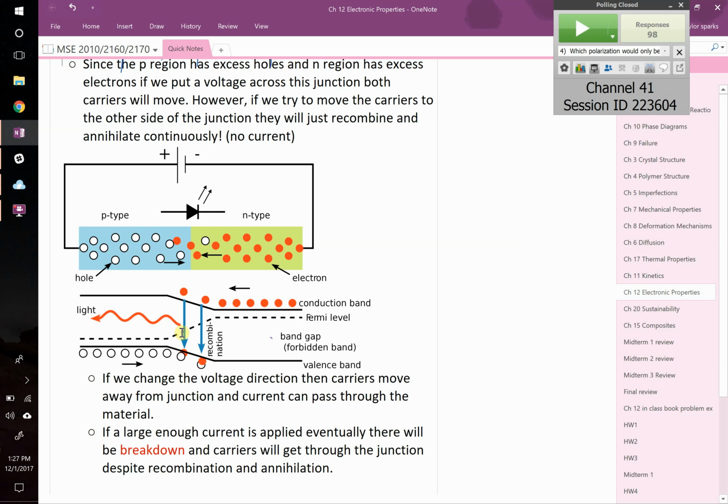So that's an LED. That's all it is. An LED is just a PN junction. You're forcing electrons to fall down and fill the valence band from their conduction band, and it gives off light in doing so and heats up a little bit. Any questions? So these devices that seemed a little bit like magical and like only electrical engineers know these things, they're pretty basic. They're simple things once you understand the idea of band gaps and band diagrams.